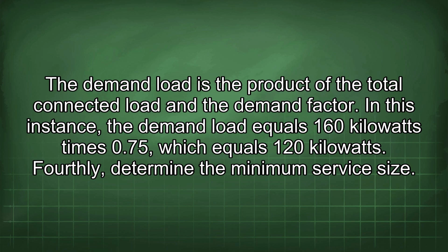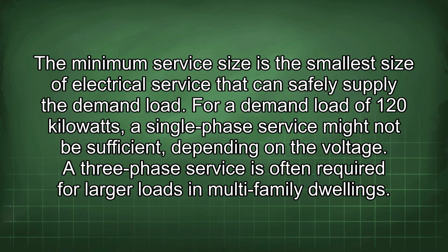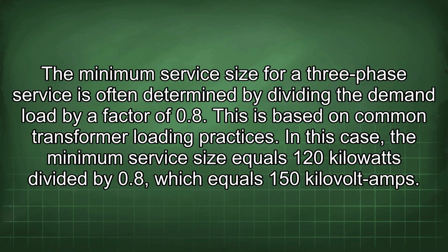Fourthly, determine the minimum service size. The minimum service size is the smallest size of electrical service that can safely supply the demand load. For a demand load of 120 kilowatts, a single-phase service might not be sufficient, depending on the voltage. A three-phase service is often required for larger loads in multi-family dwellings. The minimum service size for a three-phase service is often determined by dividing the demand load by a factor of 0.8. This is based on common transformer loading practices. In this case, the minimum service size equals 120 kilowatts divided by 0.8, which equals 150 kilovolt amps.